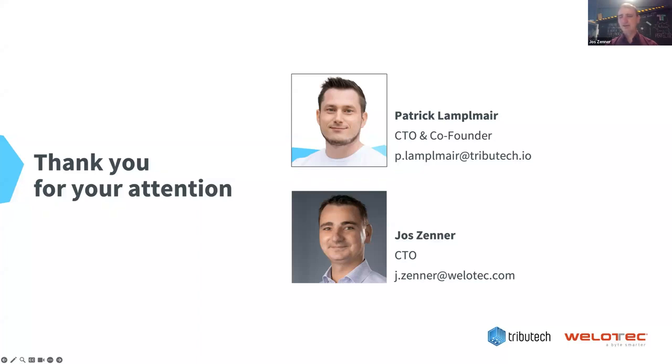All, of course, are substation certified, IEC 61850-3. So this is a wide range. For most simple applications in secondary substations, we are fine with a 4-core Atom processor with 4 GB of RAM. And this also allows you plenty of space to extend that further in the future with additional applications. Patrick, do you want to add something to that? I think you covered it already very well.